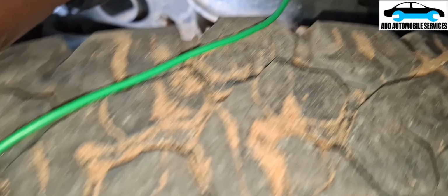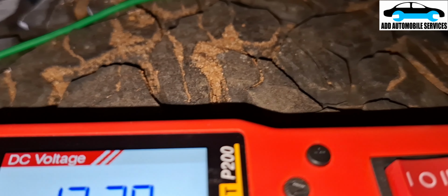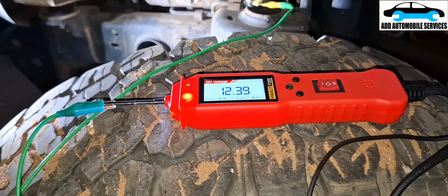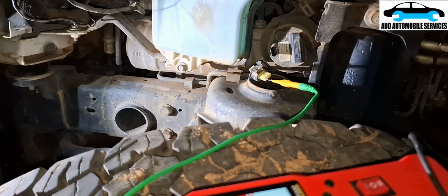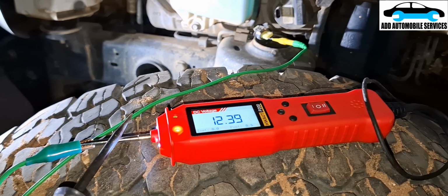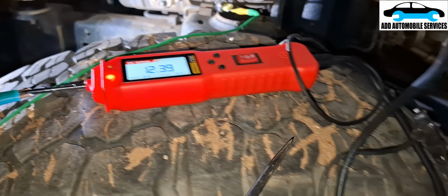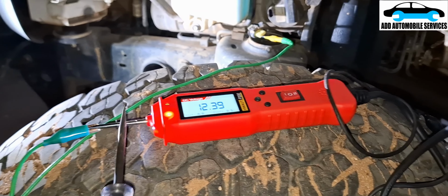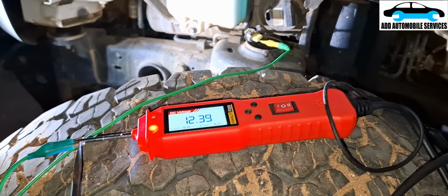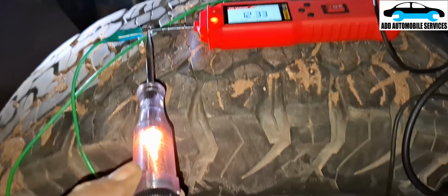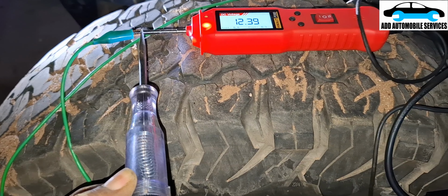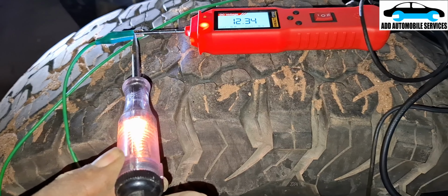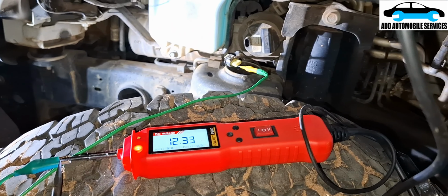Yeah, on pin 1 I'm getting 12 volts. To verify my 12 volt is a solid 12 volt, I have to use a test light to make sure it's a solid 12 volt. Although I'm getting a 12 volt, to verify it, I've connected my test lead to ground, and it should turn on my test light, and you can see my test light is on. The voltage has dropped a bit, my test light is on, so that tells me that's a strong 12 volt from there. Then let me go to ground